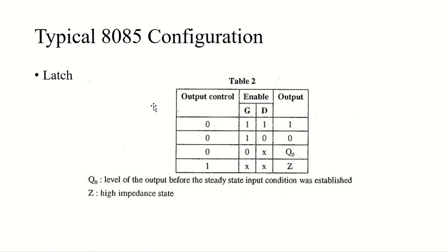You can put all 8 outputs in either state. But what happens in the high impedance state, the output neither loads nor drives the bus lines very significantly. So it does not affect the internal operation of latches or flip-flops, and because of that the old data can be retained or new data can be entered whenever the outputs are off in these conditions.